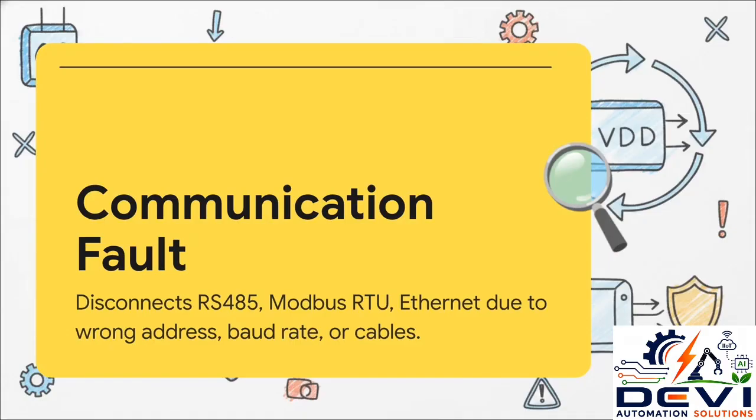And look, in today's highly connected factories, we absolutely cannot ignore the communication fault. This happens when that invisible digital handshake between your devices just drops. We're talking about your RS-485 network, Modbus RTU, or Ethernet connections. Basically, when your PLC or SCADA system disconnects from the VFD, this is the fault that pops up. And you know what's crazy? The root causes are usually so simple, but wildly frustrating. A wrong address setting, an incorrect baud rate, or literally just poor physical network cabling.